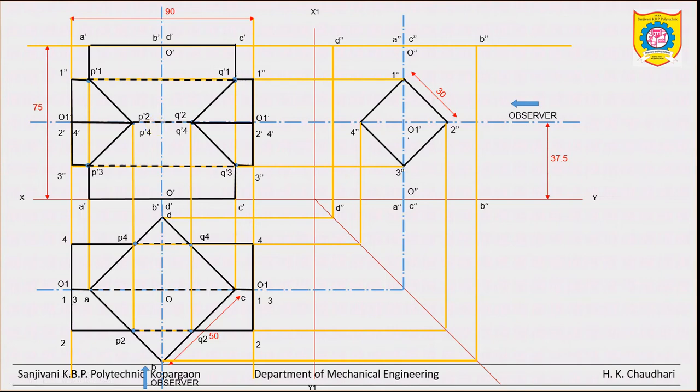Okay, now for the side view, see, this vertical edge, that means B edge and D edge. See here in the top view, B vertical edge and this D vertical edge, they are also not taking part in the intersection, so directly draw it thick. Clear?